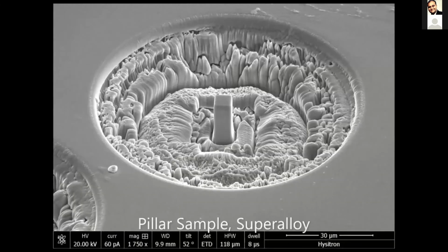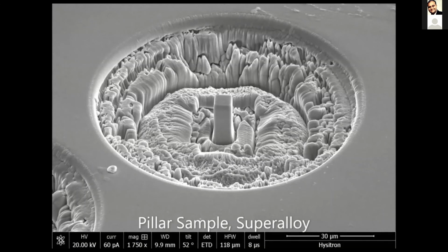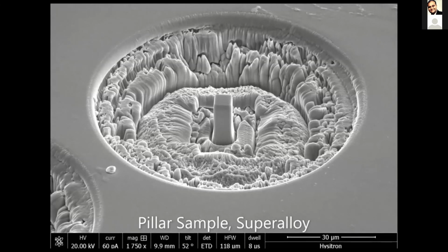Here's a much higher magnification view of one of the pillars from the superalloy. This was made by focused ion beam machining. So first you have to make a large cutout using a higher beam current to remove enough material around the pillar so you have good visibility of the entire height of the pillar during the test. Then you want to come in with finer currents to refine the shape of the pillar.